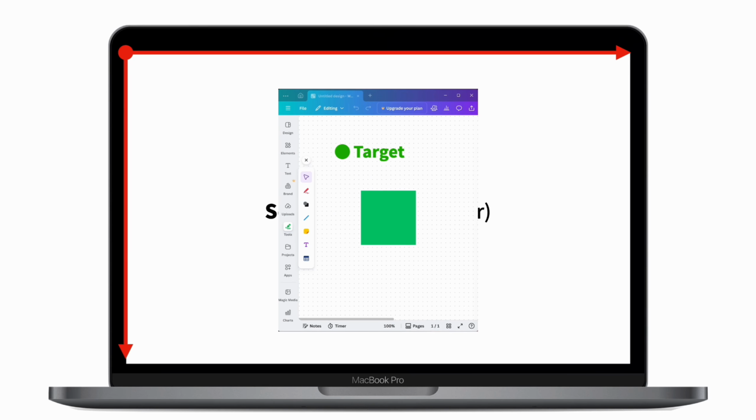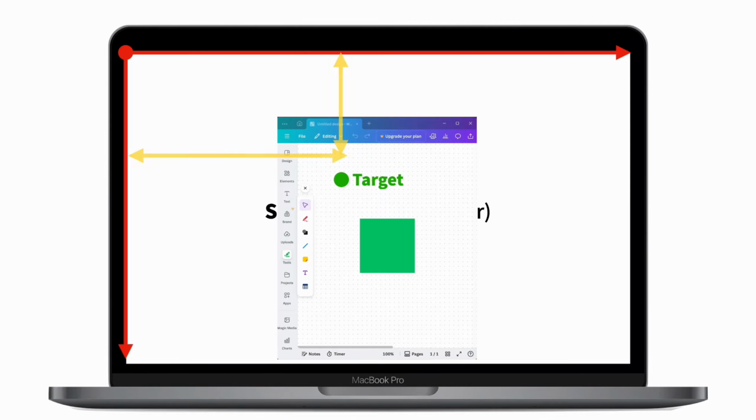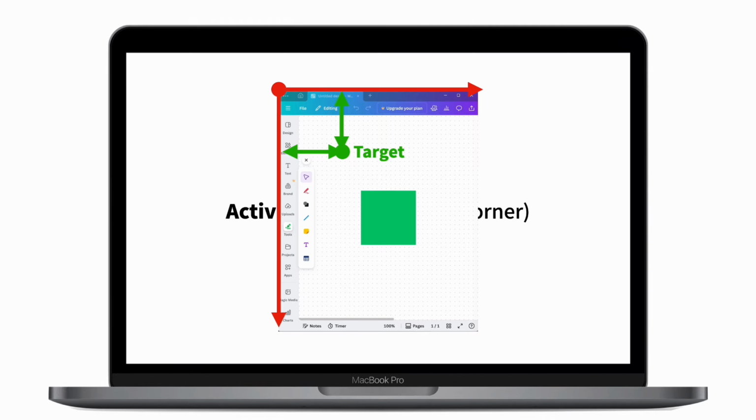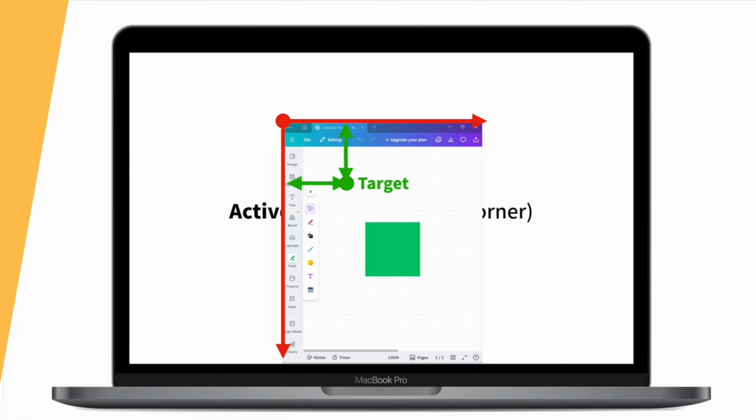The key difference between the two is this. When using the top left corner of the screen as the origin, make sure the target window stays fixed. Otherwise, moving the window will cause the target coordinate to deviate. When using the top left corner of the active window as the origin, however, you don't need to fix the window's position. It automatically adapts to window movement, making it much more flexible.